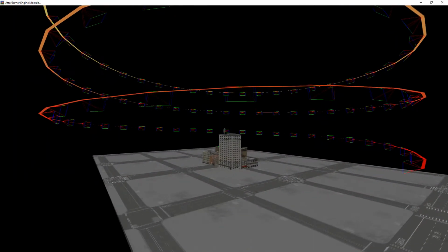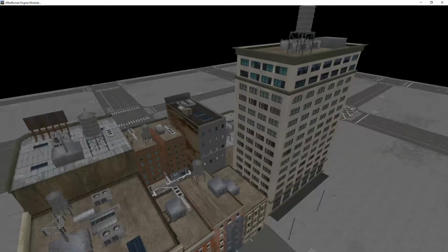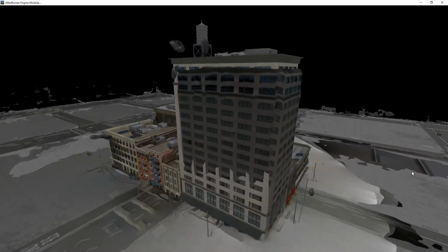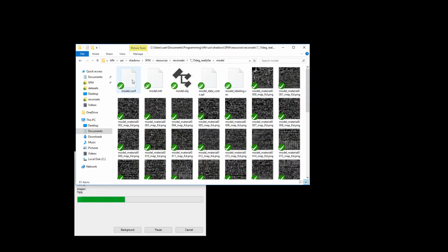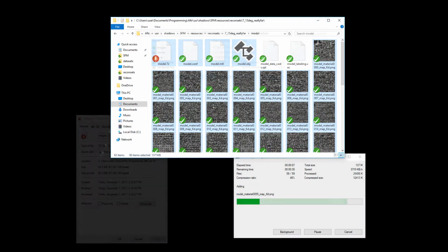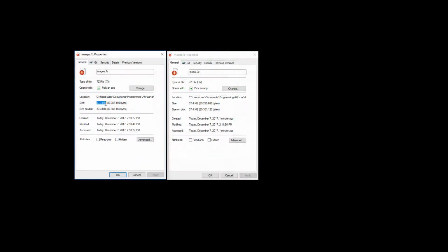This study shows structure from motion results from a modifiable spiral flight path and compares the geoaccuracy of each result. A flattening of height is observed, and an automated compensation for this flattening is proposed and performed. Each reconstruction is also compressed, and the size of the compression is compared with the compressed size of the images from which it was created. A reduction of 49 to 60% of required space, or bandwidth in a network transfer context, is shown.